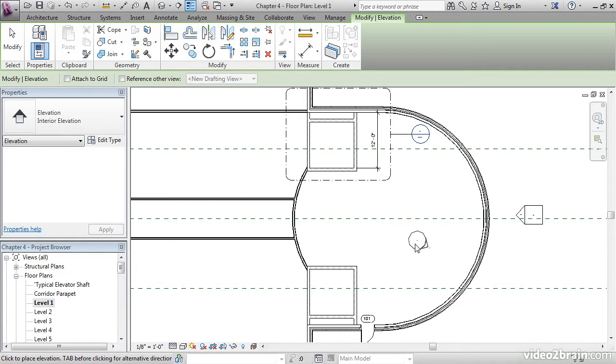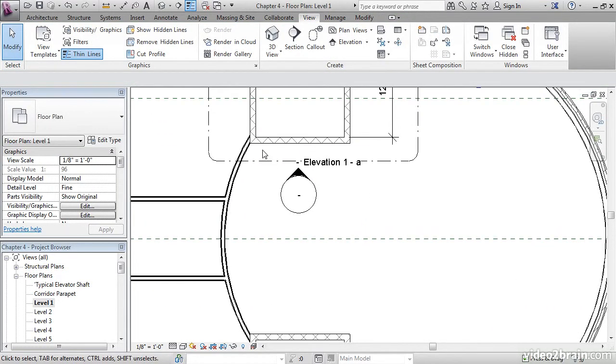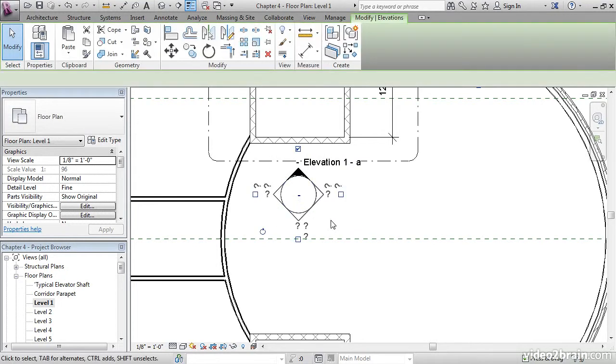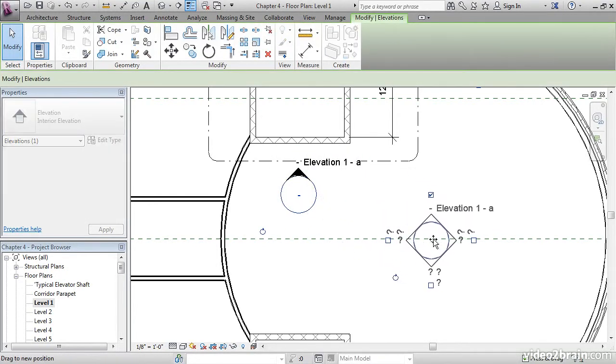If not, it might be a little bit askew if we try to beam it at another wall. So I'm going to pick this wall here, and I'm going to hit Escape. I'm going to zoom in on it. I'm going to pick a window around it, and I'm going to move this just like I moved the exterior elevation, out to somewhere that makes a little more sense.